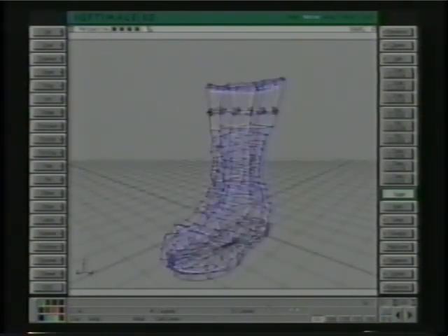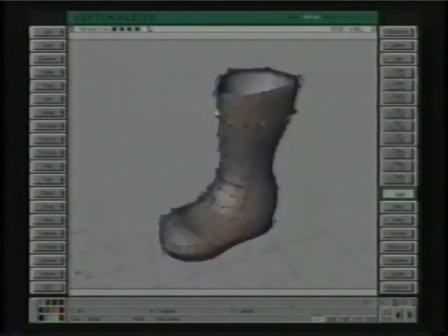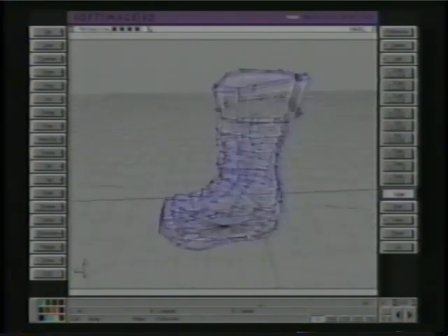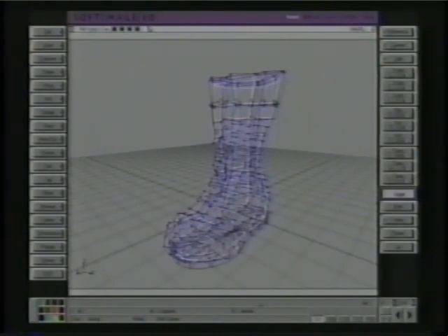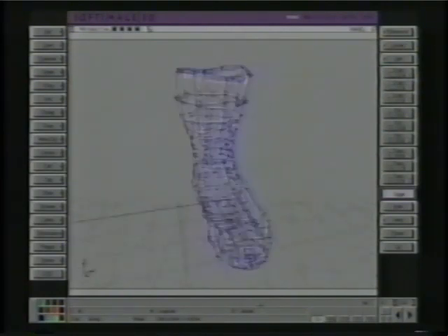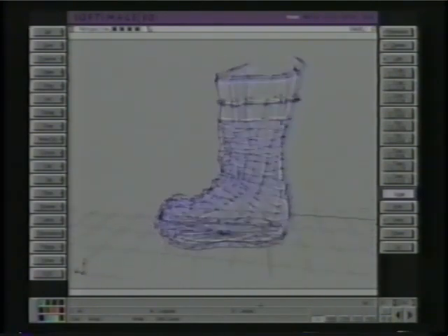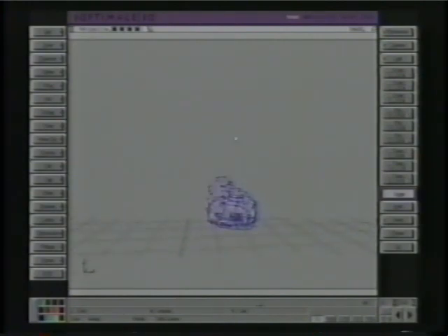And then if I frame real quick, you can bring the far plane up very fast. So you can use this with wireframe, you can use this with shaded mode, with wireframe optimization, or in shaded mode. Now later on, this slider that you've set up will conflict with the animation. You won't want that to happen while you're animating other parameters and stuff. So another thing you can do is use the custom effect depth frame, and that's under camera here. What that does is takes the distance or the length of the object and adds a little bit, and then clips the camera plane to that distance, and that's both in the near and the far plane. So if I pan in, you'll see that the front is clipped, and pan out, the back is clipped.